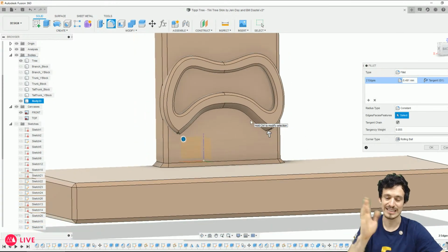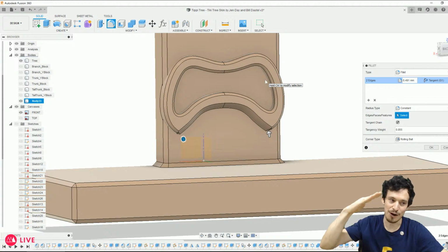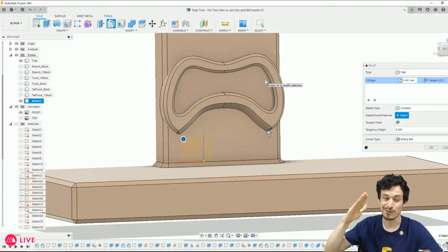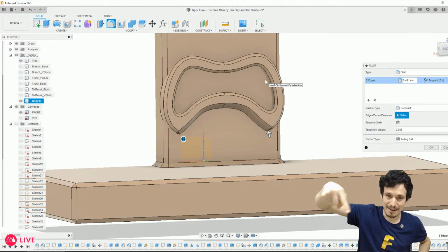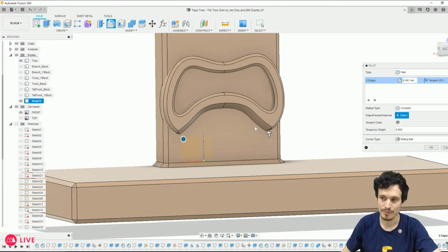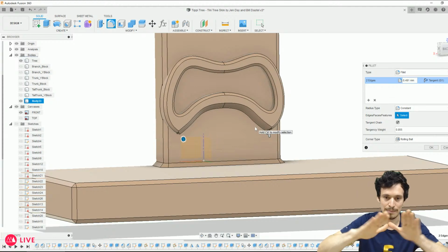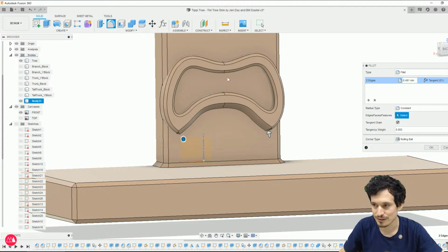You can actually get really steep if it's an underhang with a fillet. Like, there's always people say, oh, you shouldn't go above 45 degrees, but it really depends on the geometry. If it's a thin corner of a triangle going outwards, it can sometimes get way steeper. If it's just like a big flat angled ramp, then yeah, you're going to be more limited by the angles.